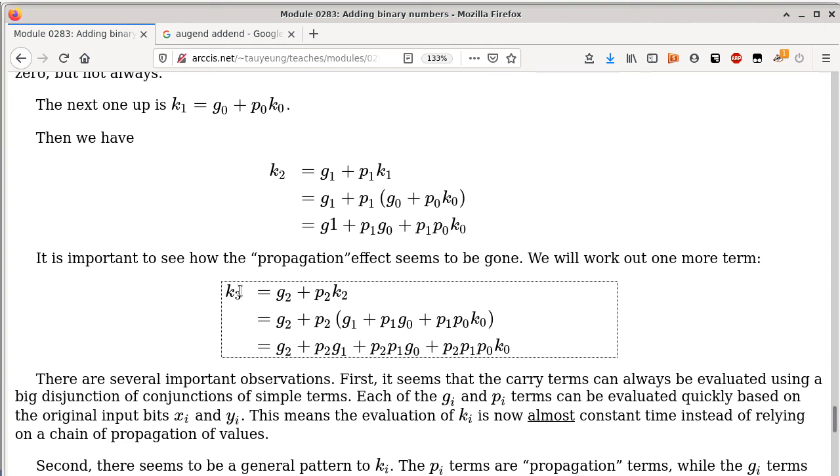It would take, in theory, the same amount of time to compute. And it does not depend on the carry bit right before it. They only depend on the X, the Y, and the K0, which are all input pins. So are we getting the general idea of what carry look ahead is? It gets rid of the interdependency between the carry bits. Is that okay? So you look at this and go like, okay, Tech, I challenge you to give me K64.